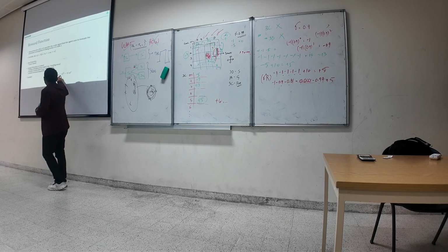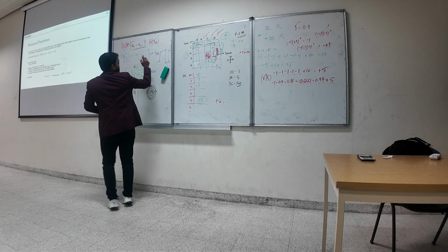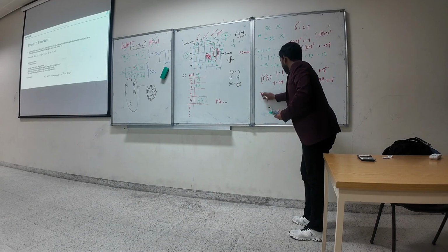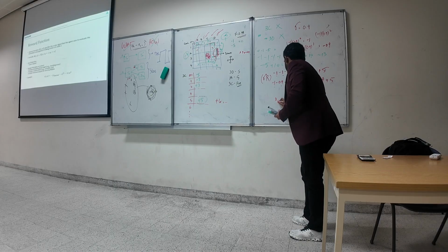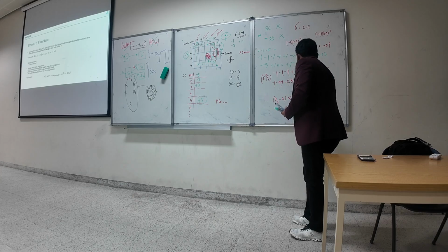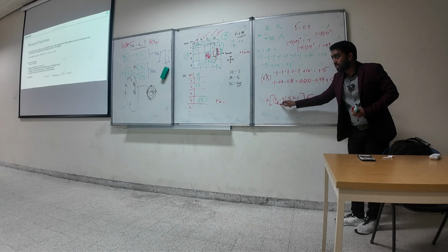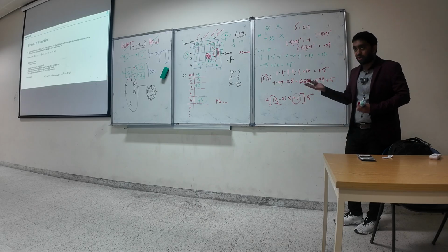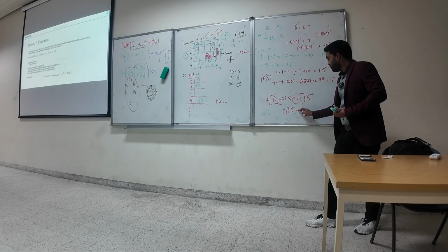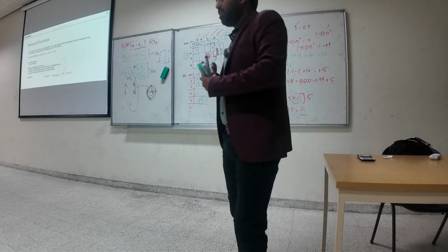Say plus 10 if x desired minus x. You could have conditional reward functions. Reward functions need not be continuous, right? So you can simply have, apart from that reward, a last term, something like this. If x desired minus x is less than 0.1, then multiply this by say 5, plus 1. So it means when your distance error is less than 0.1 or whatever threshold you define, then this value will simply become 1, right? And you multiply it by 5, so you get plus 5. You could have that as your terminal reward function.